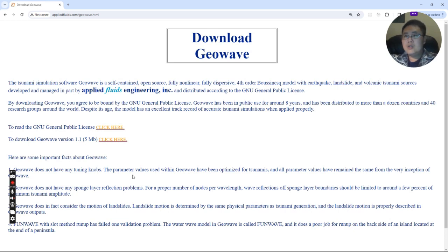And this particular code for generating the initial conditions used for funwave-tvd only requires one input file, which is the bathymetry. And when you run this code, it's going to ask you lots of questions about the tsunami source, right? And if you answer those questions correctly, then it's going to create the right initial conditions, right? And then those initial conditions, after you convert the format into the format that's required by funwave-tvd, can be used as those initial condition inputs that you specify in that control file, input.txt, right?